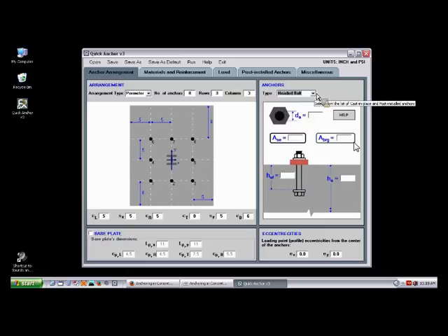So you select your type of anchor. It could be headed, let's say it is headed bolt. Then you enter the anchor diameter, which is effective in resisting tension. And that is basically the nominal diameter minus the area taken up by the thread. You need to deduct that amount to get the solid cross-sectional area of the solid shank of the anchor. So you can always type those values in if you know your values. The anchor diameter, well, this is the nominal diameter, and here you enter the effective cross-section area where you deduct the thread.